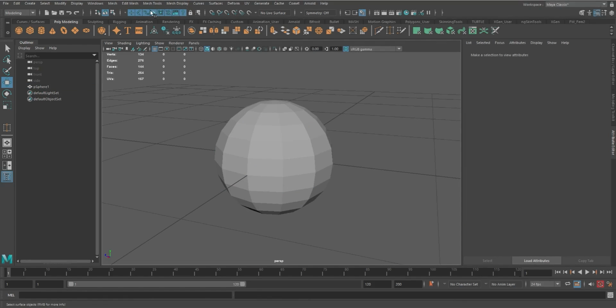That actually helps. This menu right here is a masking. It's kind of a selection mask. So if you don't want to select surfaces, you can turn that off, and then it won't let you. If you just want to select joints, you can turn everything off and have just skeleton joints in the selection mask turned on. This is where you can turn on locators and other items.